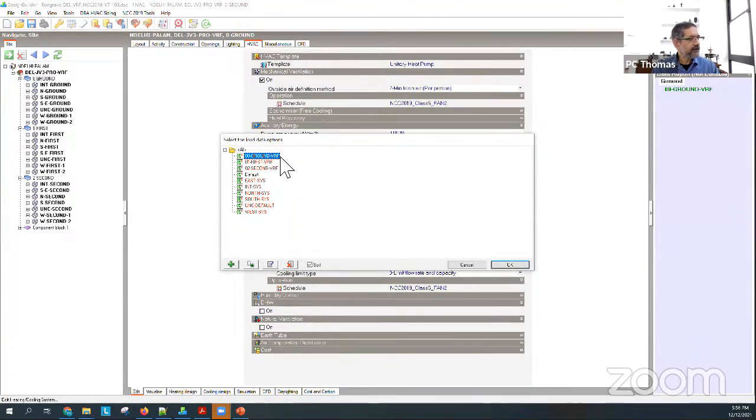You can see I've got a ground floor, a first floor, a second floor VRF. And then I added an unconditioned default. I don't want to put anything in the default system because there's some calculation error that's happening, which we have spoken to DesignBuilder about. They're correcting it. But if you leave it on default, it does something weird. So don't leave anything on default. Just create an unconditioned default system and put all the zones that are not conditioned into that, okay?